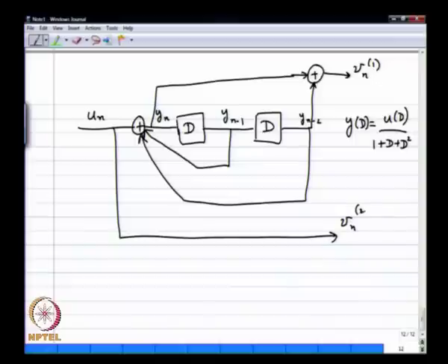This is a very standard implementation in DSP for the IIR filter. I think it is called type 1 or type 2 or one of those types. There are also other names for it, observer canonical, controller canonical, all kinds of names for these implementations. The standard pictures for linear systems you might have studied at some point, but even otherwise this is a good refresher.